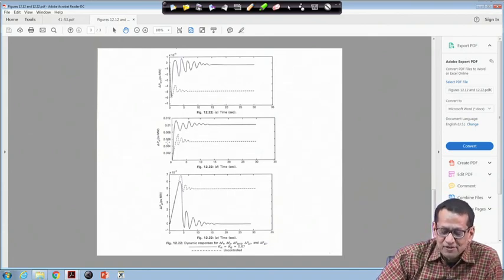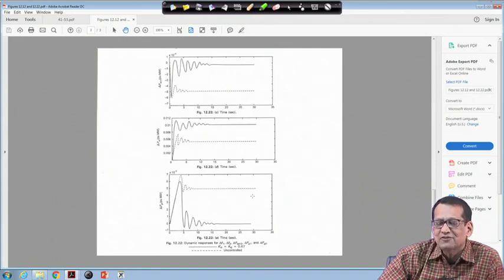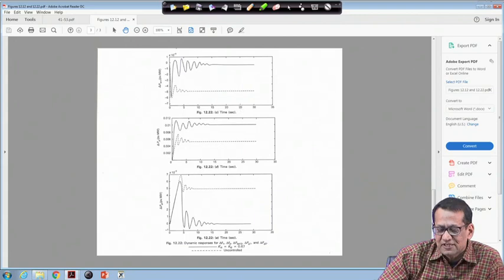And similarly, for delta Pg1 and Pg2, the load disturbance has happened in area 1. When uncontrolled, both are generating 0.005 per unit megawatt, because both are uncontrolled. So, both areas share the same generation at steady state, 0.005 and 0.005, right. But when area control is there, for frequency bias I told you B is equal to beta. So, B1 is equal to beta 1, B2 is equal to beta 2.